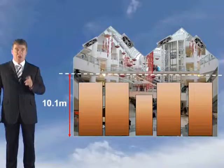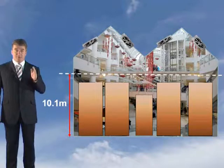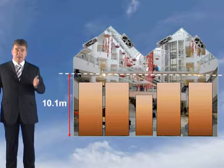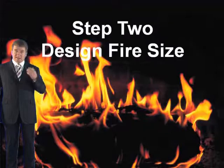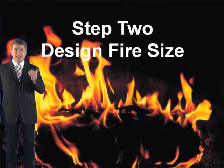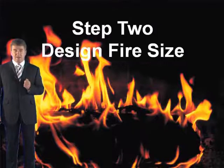They want you to ensure that the smoke layer is maintained at least 0.5 metres above the stock in the building, and this will give a clear layer height of 10.1 metres. That's step 1. In step 2, you need to determine the design fire size, and this obviously is going to be used in all your calculations. And this obviously is the worst case scenario.